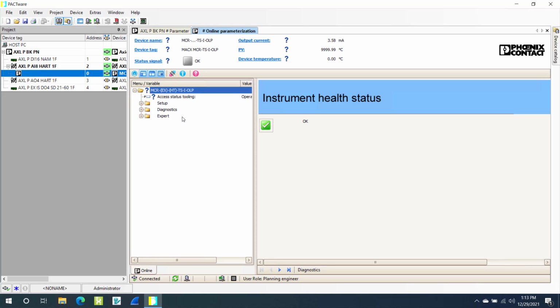Now, this is one of the largest benefits that you can get with the communication DTM: using the acyclic P and the acyclic F with the PLCnext 2052, you can tunnel down into the connected HART sensor's vendor-specific DTM. So you see the screen here. It's a Phoenix Contact device. Looks very similar to Endress+Hauser, but it's a DTM, in this case from Phoenix Contact, a vendor-specific DTM. So this has nothing to do with our Axioline I/O module. We're just using that I/O module to tunnel down through and find information, read information about the device and parameterize it.